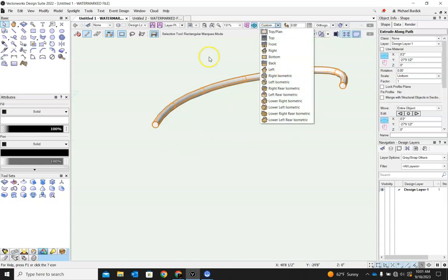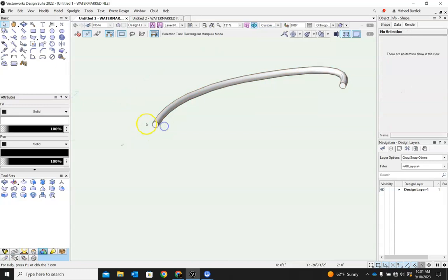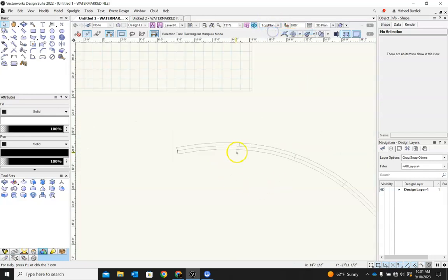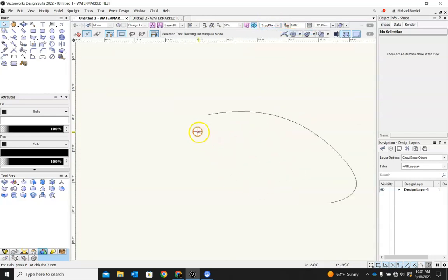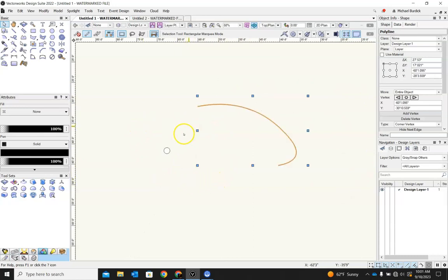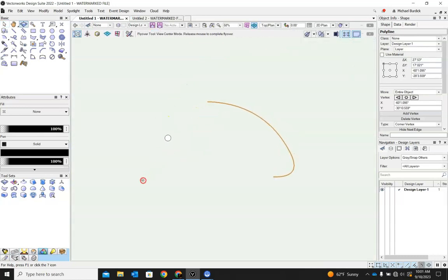So in that instance, just as a way to demonstrate how this kind of works, I had the profile touching on the path. But more often than not, you're going to just want to draw your profiles anywhere. It makes things much easier. So your profile and your path don't actually have to be touching or in relationship to each other pretty much at all.